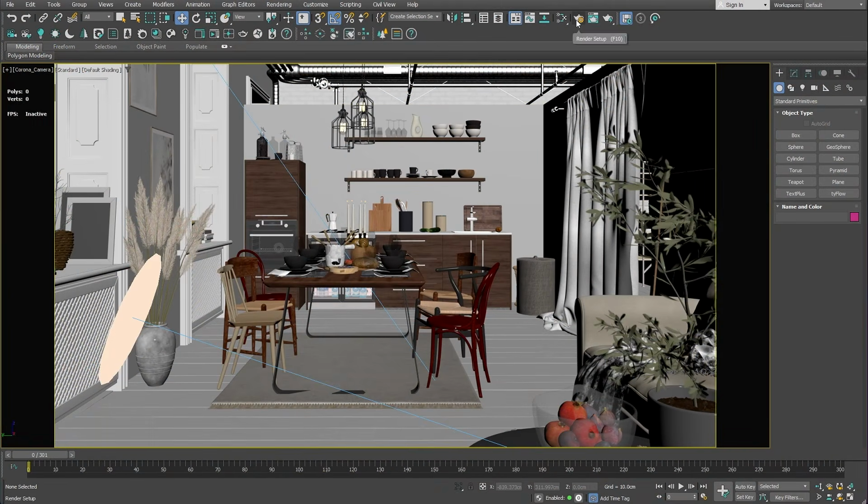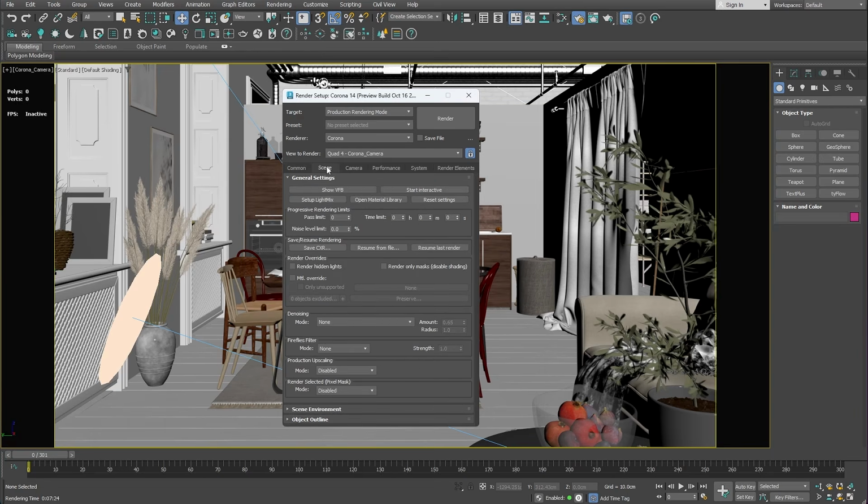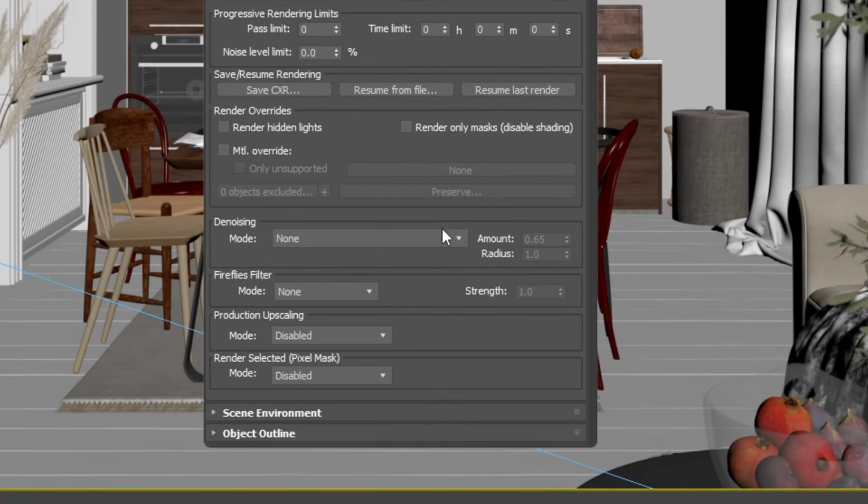First, open the Render Setup window. Since our final output is Full HD, we'll double the resolution to 4K. Next, go to the Scene menu. Here's the key step. Enable Intel AI Denoiser. It's the best option for final outputs. Keep your geometry and textures consistent.